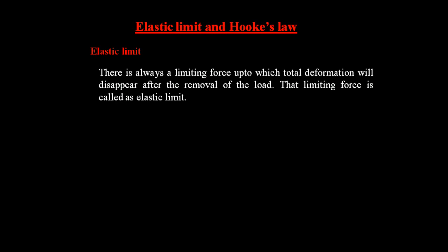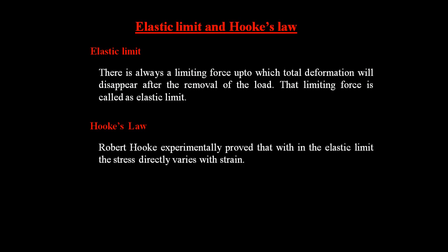Next we go for Hooke's law. What is Hooke's law? With the help of the elastic limit, Hooke's law gives one statement. Robert Hooke experimentally proved that within the elastic limit, the stress varies directly with strain. That means stress is directly proportional to strain within the elastic limit.